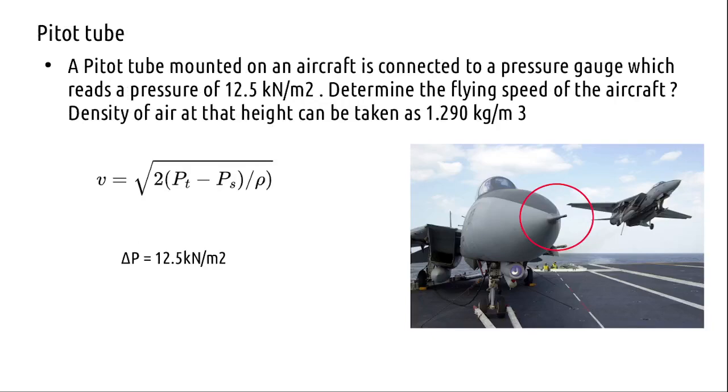The final thing is about a Pitot tube. In fact this Pitot tube is mounted in an aircraft. So it's a fighter aircraft, and unlike commercial aircraft, fighter aircraft mount the Pitot tubes in the nose cone here in the forward part. Commercial aircraft you will find it in this portion. Pitot tube failure is going to give you wrong indication of the airspeed. Whatever you measure using a Pitot tube is called airspeed.